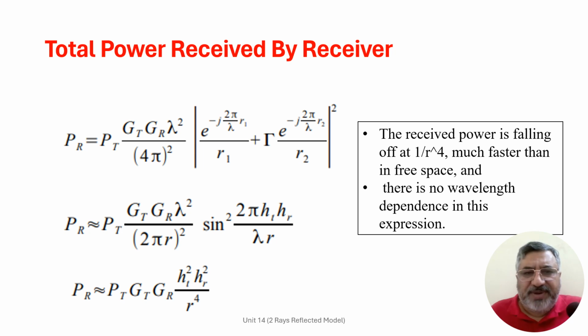When both are present, we cannot simply add the power, because it is an electromagnetic field that we can add, and the field has both amplitude and phase. The amplitude is proportional to the square root of the intensity, and the phase is the distance traveled in wavelengths. The amplitude of the reflected field can also be calculated by multiplying by the reflection coefficient of the ground.